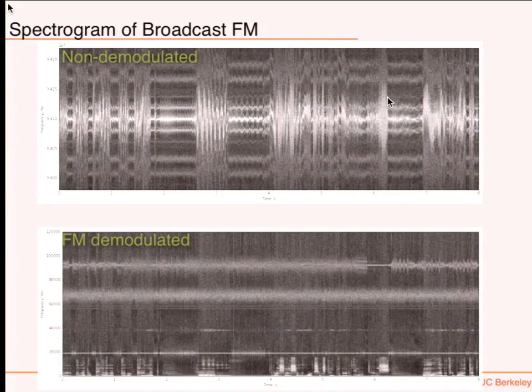There's a trick that you'll do over there. Basically, do things in the complex domain, but all the instructions tell you how to do this. It goes through the derivation very nicely. But you see how simple it is to build an FM receiver when you're writing it in Python as opposed to making a circuit. The circuit's now done for you. It does a lot of other things, but now you can just take those samples and do an FM demodulation, even though this chip is meant for something else.